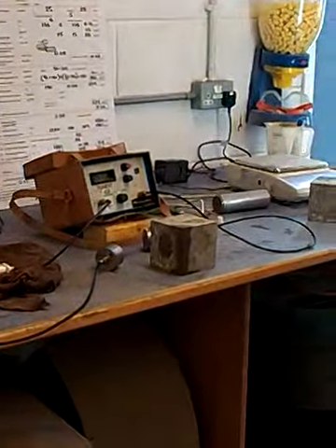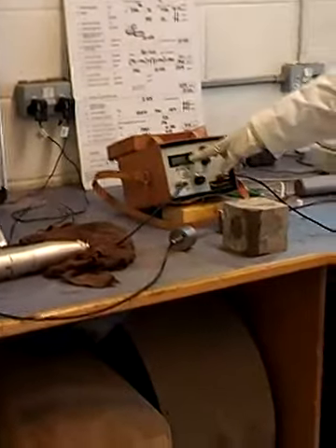Right, okay, you got 3 range topics, right? Now, from this one, you got this one in microsecond. Now, are you clear with these things? What should be done to calculate the velocity? Okay, so you got microsecond, convert that to the second, and velocity comes in kilometer per second, then compare that to the quality of the concrete.